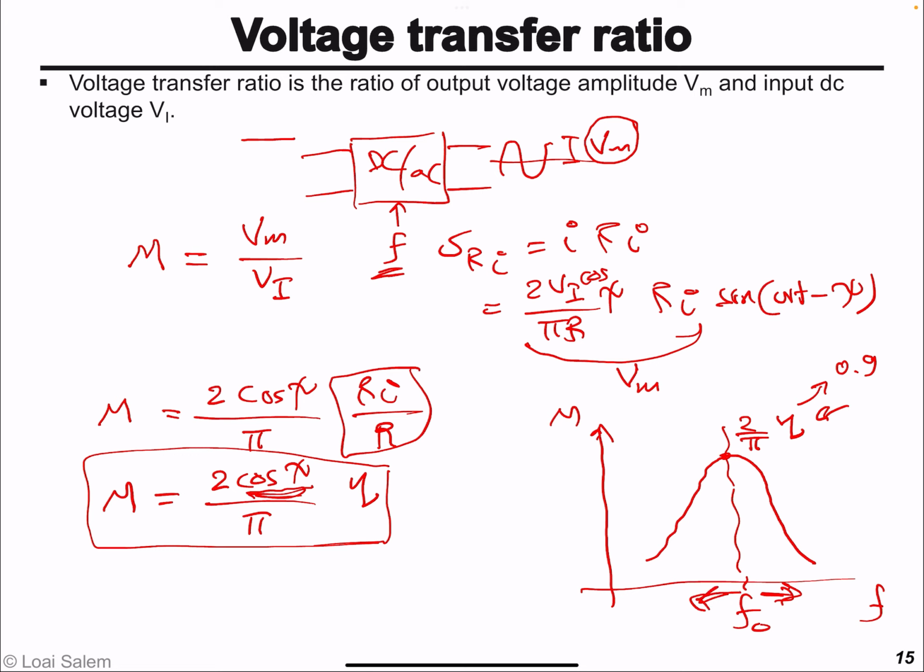Of course, typically we operate above the resonant frequency so that we enable zero voltage switching, but that's a little advanced. But anyway, as we deviate from the resonant frequency, we'll find that the amplitude of the output voltage is going to decrease, right? So that's one way, controlling or tuning f around the resonant frequency to control the amplitude of the generated AC output voltage.